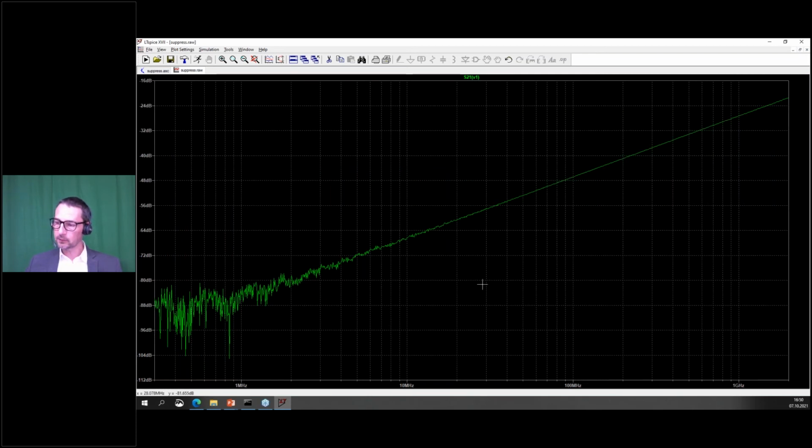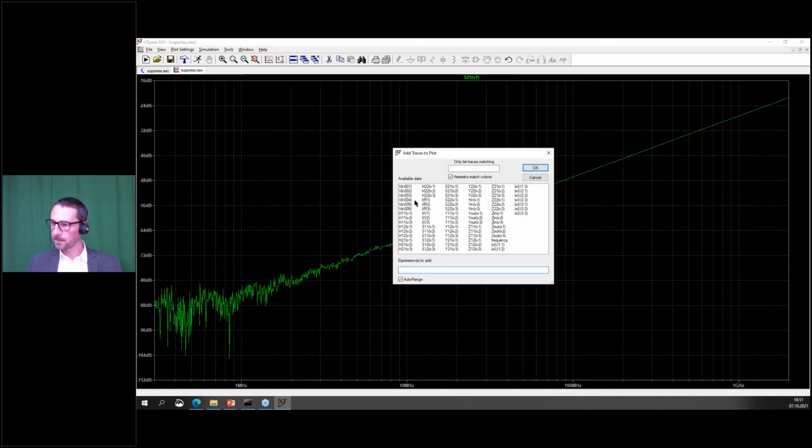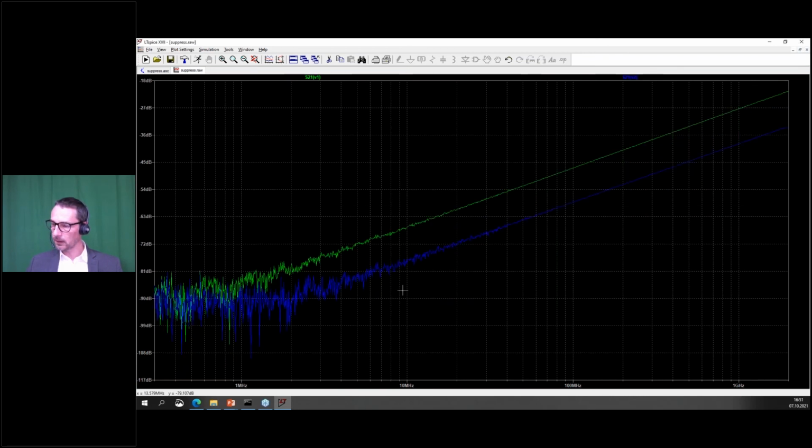Now we will add the second trace, which is the diagonal pins. So just shifted 1 pin row to see how big the impact is on the result and how much more you can gain with that. And this would be now my version 2. If I add it, I can see already only by increasing the distance a little bit, I gain more headroom for that.